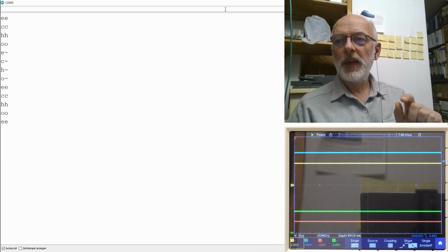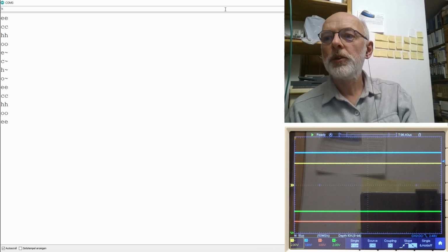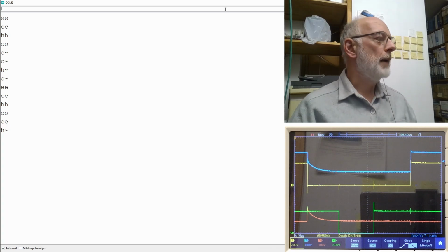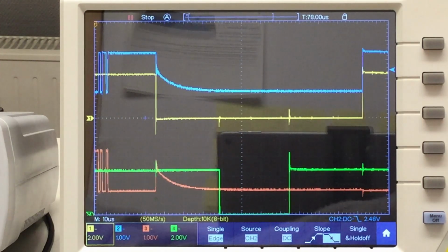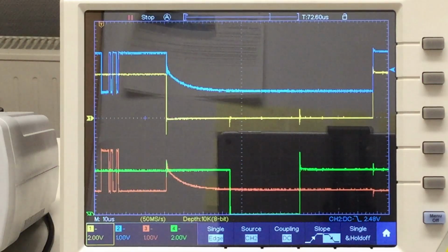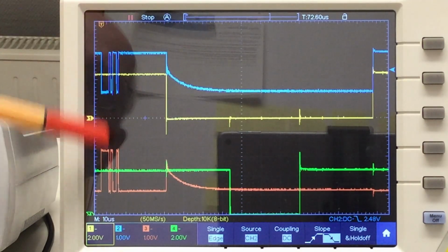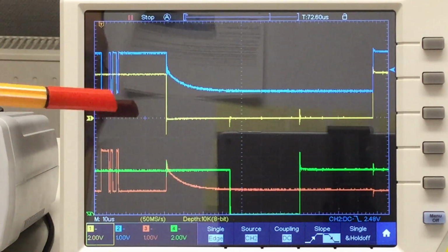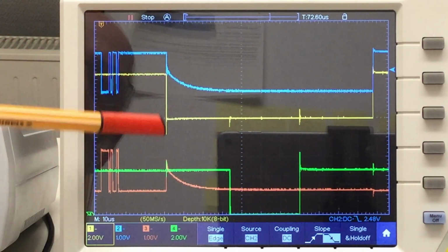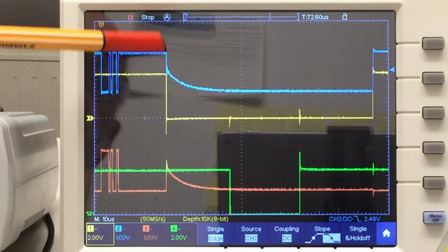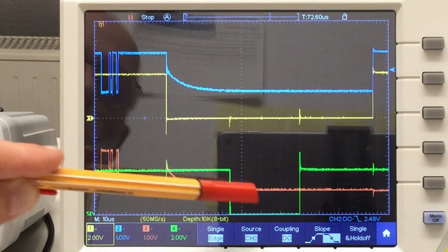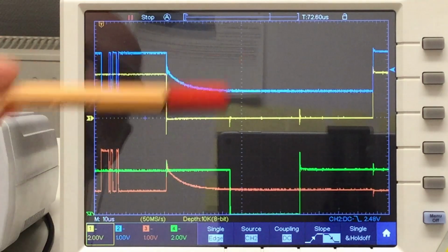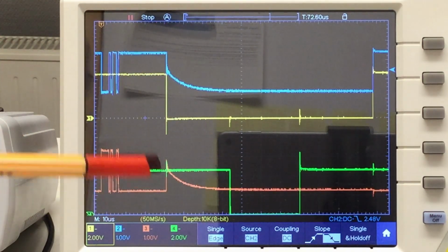Now let's do the same with the slave turned off. And yeah, we have here a timeout. Scrolling to the start again. Here's, like last time, the byte transmitted by the master, but of course there is no slave receiving it. The master anyway disables its transmitter and the bus goes into an undefined state, and it stays in that undefined state because our slave is dead.